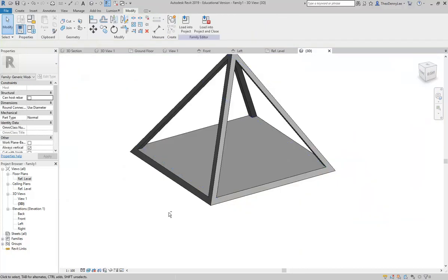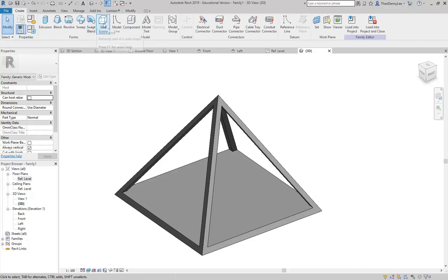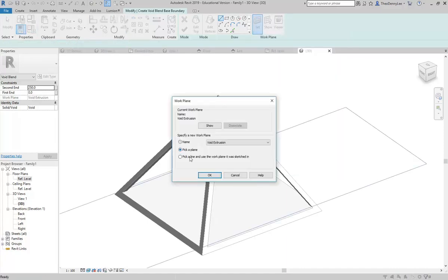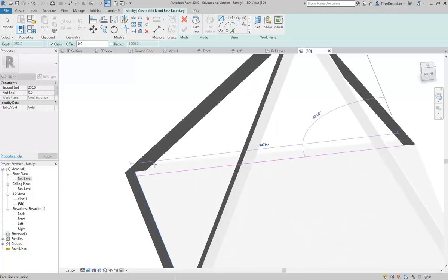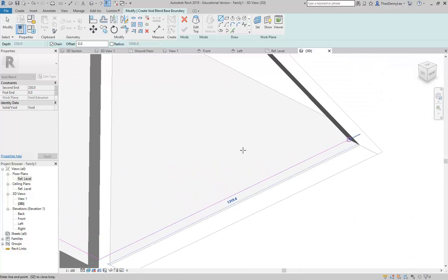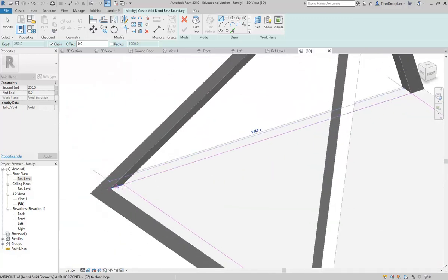It's interesting. So, okay, doing a blend, I'll, again, go to void forms, but this time void blend. So again, I'm going to choose Set and pick a plane, and then make sure I get that surface, basically to make it easier to snap to these corner points. And right, so that's the same as the extrusion that I just did.